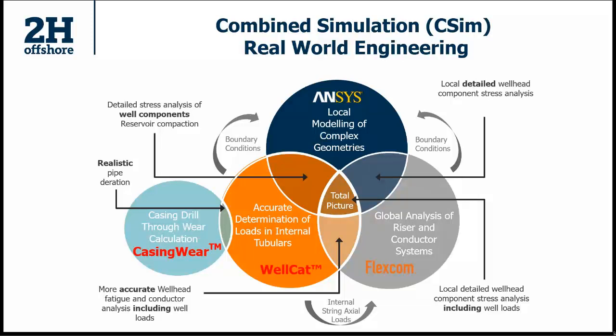The relationship between FlexCom and ANSYS is quite well entrenched in the industry. The idea is you do your global analysis in FlexCom, and then if required, you take those and apply them as boundary conditions to things like a detailed wellhead stress analysis in an ANSYS model. So you apply those boundary conditions from the global package and apply it to the detailed ANSYS package.